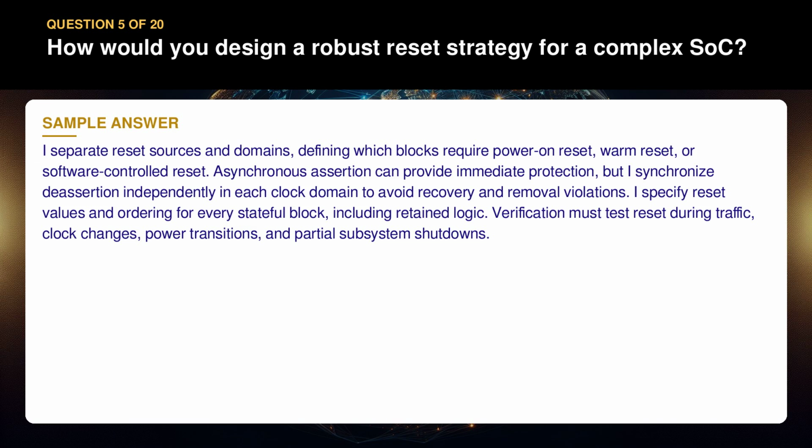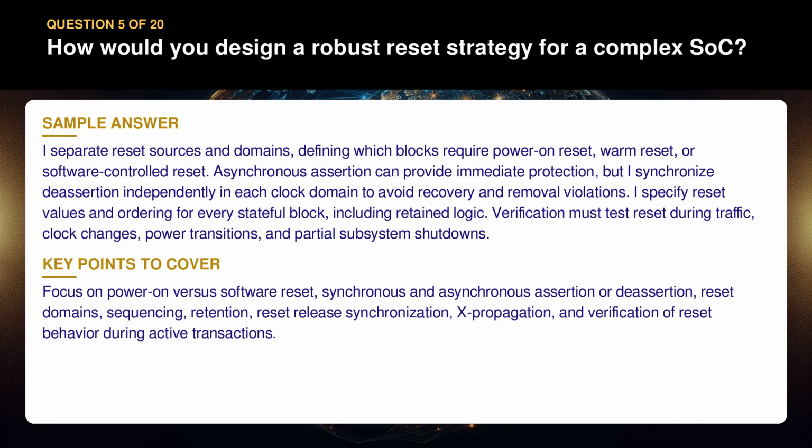Verification must test reset during traffic, clock changes, power transitions, and partial subsystem shutdowns. Focus on power-on versus software reset, synchronous and asynchronous assertion or deassertion, reset domains, sequencing, retention, reset-release synchronization, X-propagation, and verification of reset behavior during active transactions.